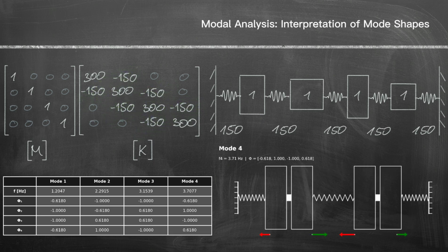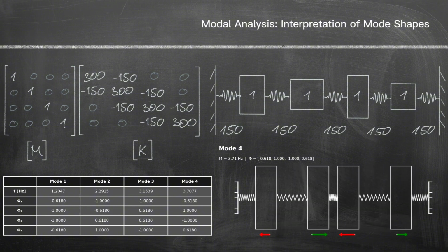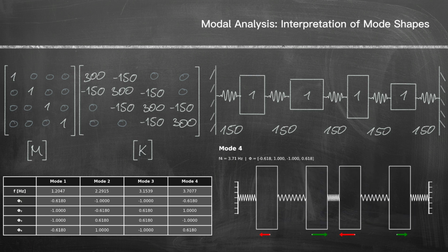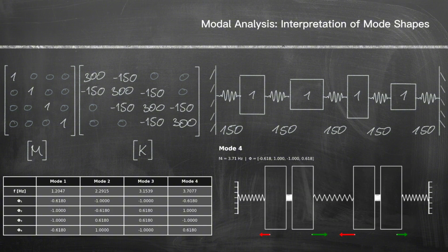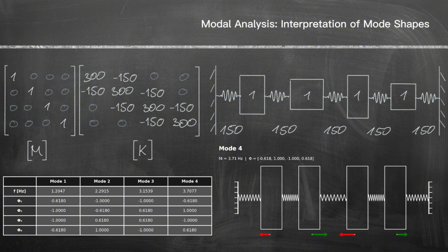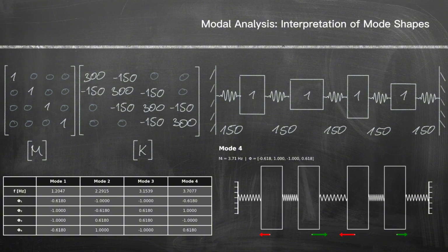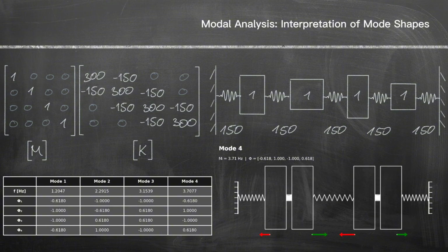Higher modes introduce sign changes and internal deformation, but still remain spatially balanced because no entry in M or K breaks the symmetry. This reference case is crucial. It establishes a baseline where the mode shapes are governed purely by connectivity, not by dominance of mass or stiffness. Every deviation we introduce next can be interpreted as a deliberate modification of specific matrix entries.